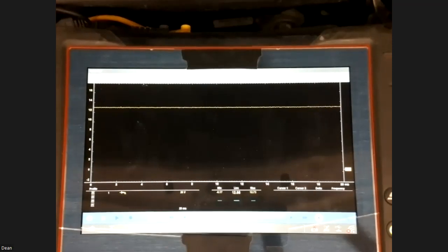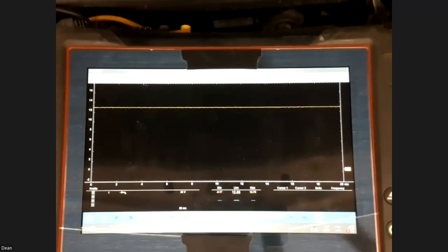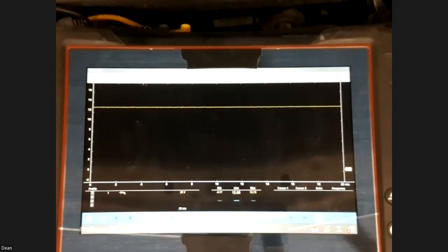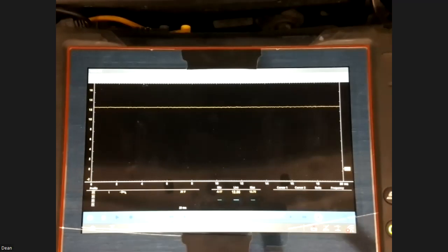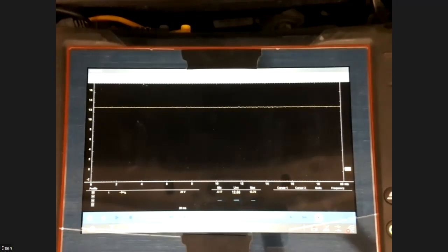Now, what's RC? All these computers. So if I go and turn this key on right now, those voltages are going to drop. And then when I go to crank it, when I put the load on the circuit, the fuel pump is running, the injectors are running, the coil packs, which are step-up transformers, that's what they are today, they're going to need 12 volts. So it's going to pull all these voltages down. All these computers online, they're going to need, guess what? At least no less than 9.75 volts.